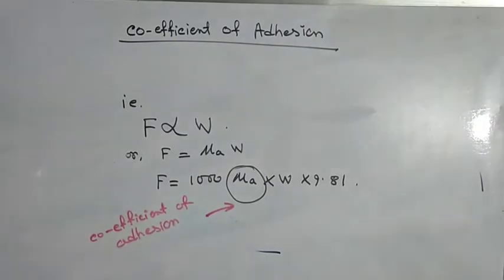This means to haul a given train, there is a certain minimum weight of locomotive. Again, the maximum allowable weight on each driving axle is limited by the strength of the track, bridge, etc. to between 15 and 30 tons. Now, if this value is known, the number of axles can be obtained.